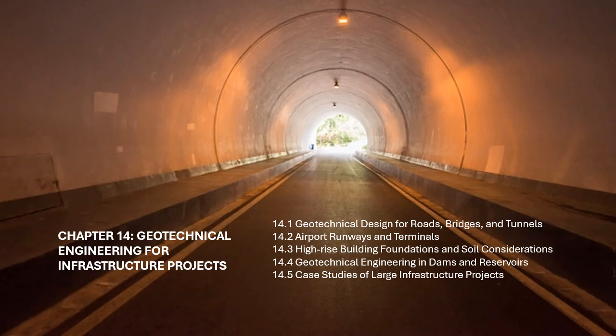Deep soil mixing. DSM, deep soil mixing, involves blending the soil with cement or other stabilizing agents to improve its strength and stiffness. This technique is used in areas where traditional foundation systems are not feasible or when the soil is prone to liquefaction.